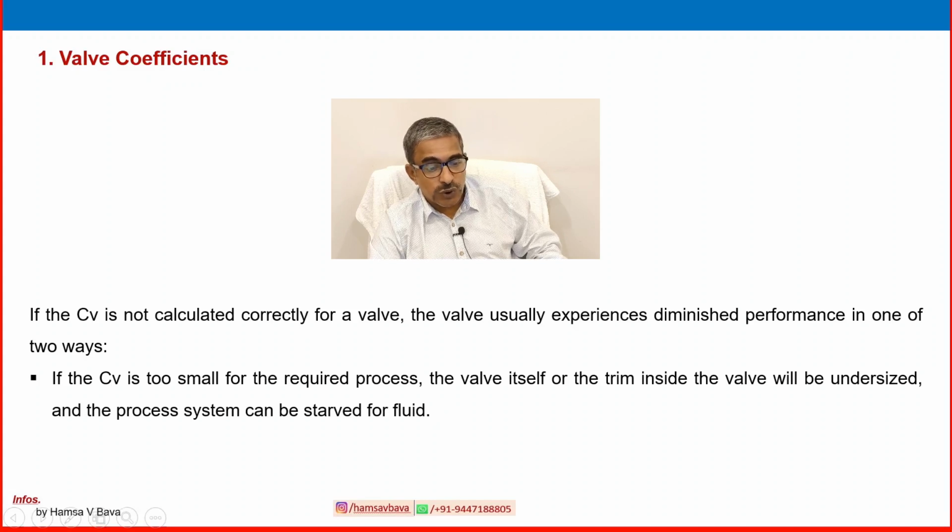If the CV is too small for the required process, the valve itself or the trim inside the valve will be undersized, or the process system can be starved for fluid.